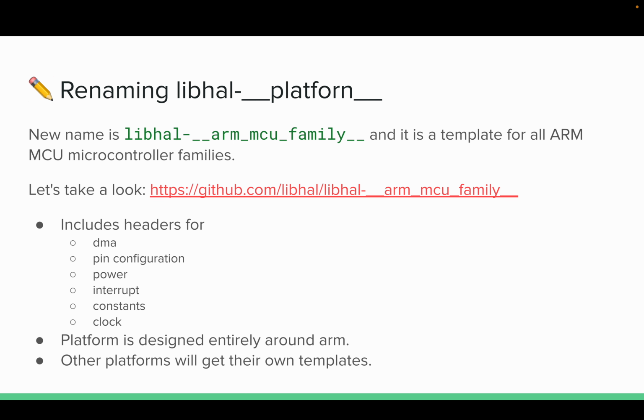And when you do initialize, you need to provide it a compile time number for the maximum number of interrupts that the system can support. Initialize interrupt will allocate that memory statically and then bind the interrupt table to that bit of memory, and also sets it up and all that stuff. So yeah, that's pretty much the bring up guide.